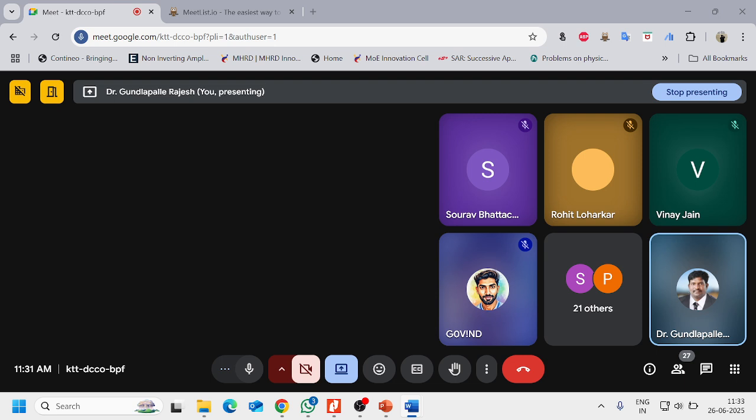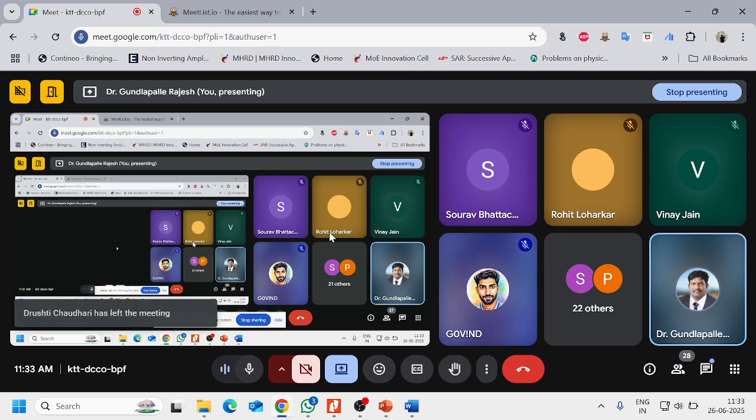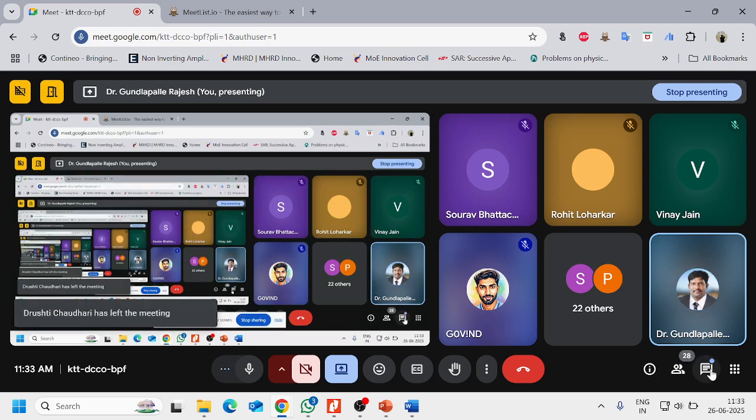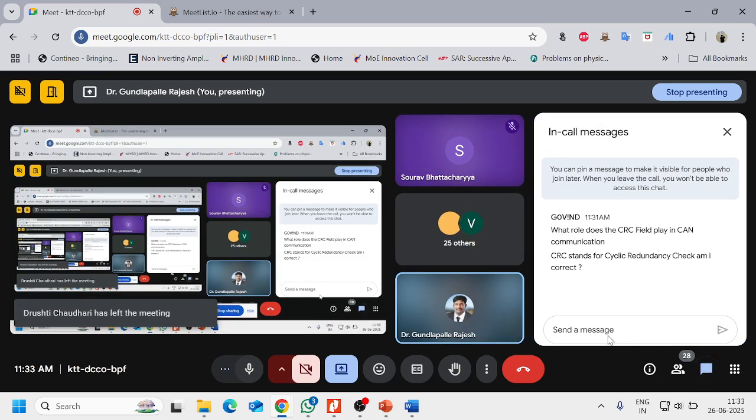So now this might be the quotient we are receiving. Now see here, these both do not match. When these both do not match, the error has been raised. The receiver will see that it has received an error message, and it will acknowledge to the sender, stating that it has received the error message, through the error frame. So for that only, your CRC checksum will be used. Yes, cyclic redundancy check.